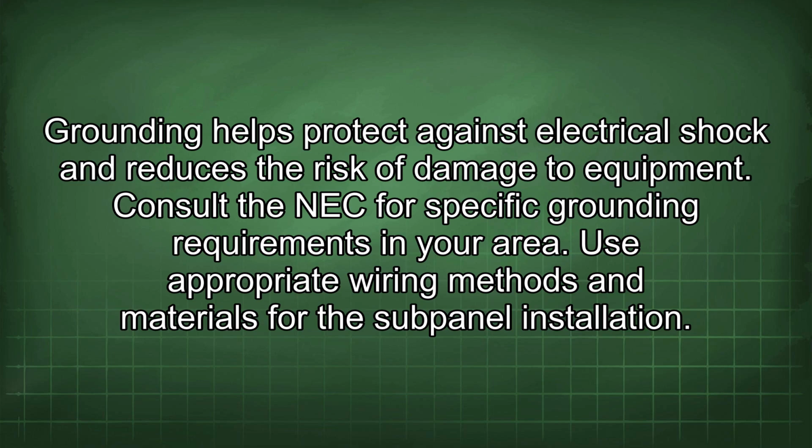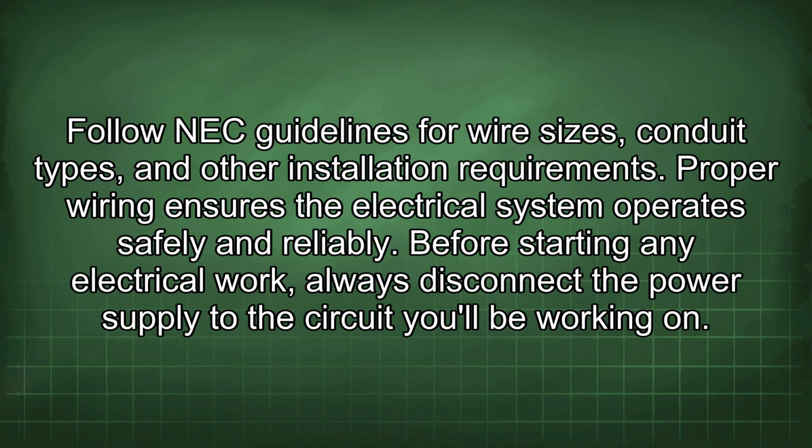Use appropriate wiring methods and materials for the subpanel installation. Follow NEC guidelines for wire sizes, conduit types, and other installation requirements. Proper wiring ensures the electrical system operates safely and reliably.